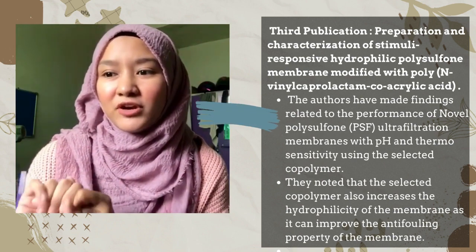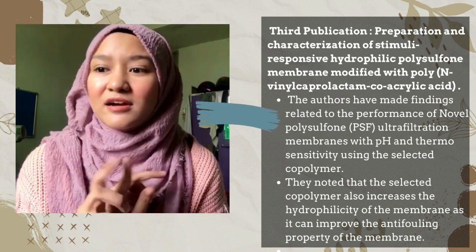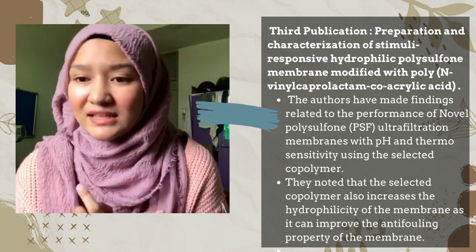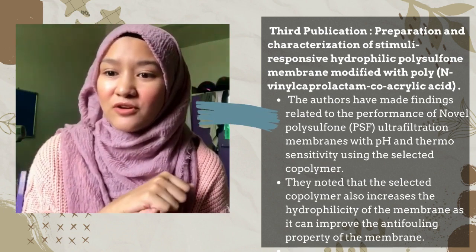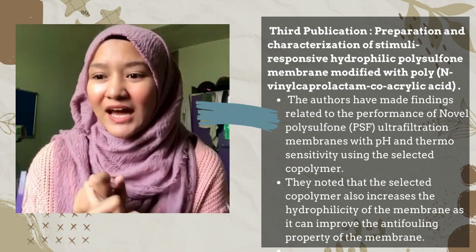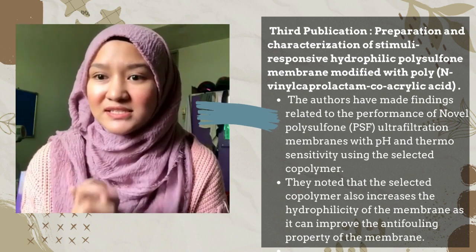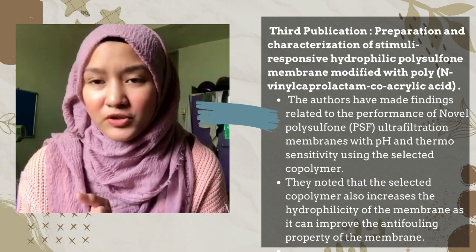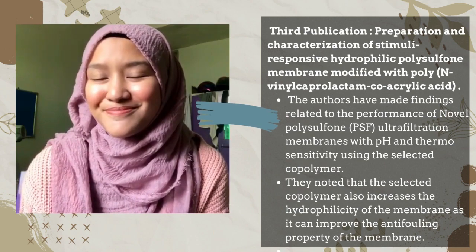Sinha et al. did highlight the importance of pH and thermoresponsive materials as they mainly focus on the preparation and characterization of the dual responsive membrane using a pH and thermoresponsive copolymer. As the authors stated, pH and thermoresponsive properties will be important in various separation and purification technologies. Next, the authors also investigated the permeation and anti-fouling performance of the prepared membrane, and they noted that the selected copolymer also increases the hydrophilicity of the membrane as PAA contains carboxylic groups. Due to the hydrophilic nature, it can improve the anti-fouling property of the membrane.